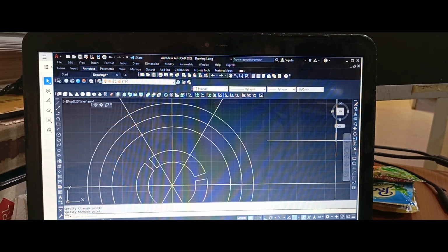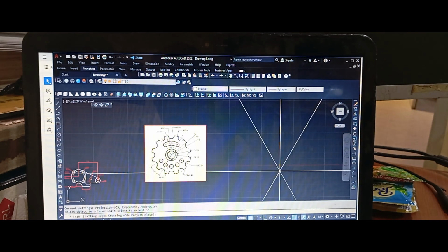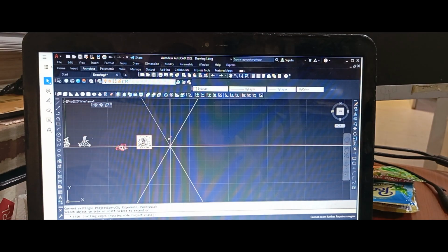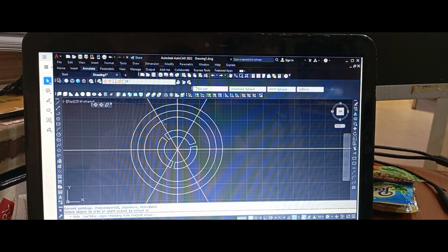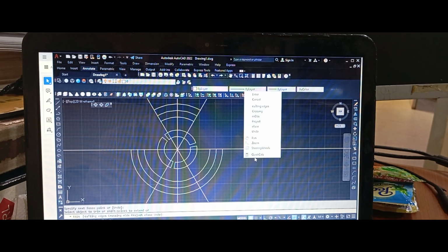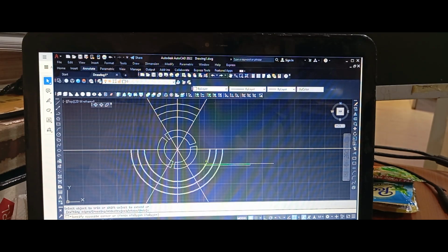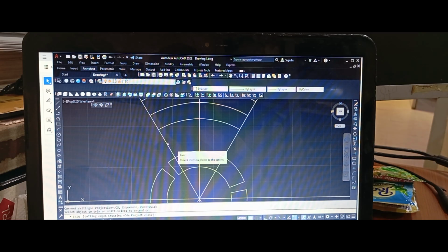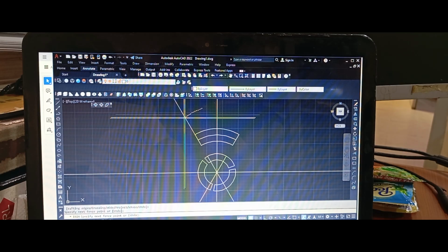I'm going to cut all this half. If you look at this drawing, I'm going to cut off this circle. So I've got a circle that will form here, semicircle, I'll trim from here. So I'll remove all this. Yes. So I really don't need this down. The drawing does not tell me I'm going to need this. So I'm going to trim off this. Trim this. And this. And this. This is going to go by erase.